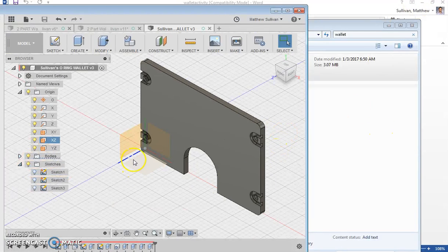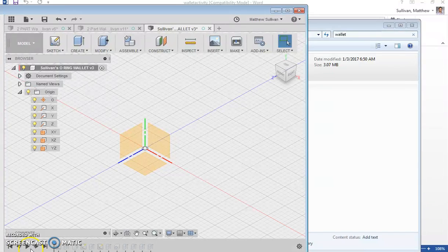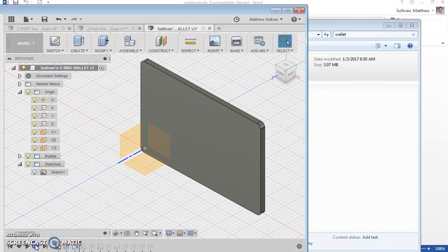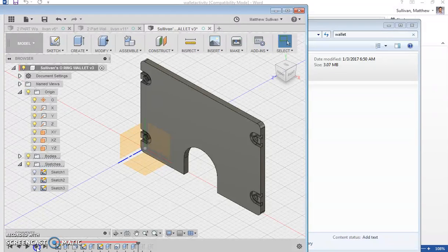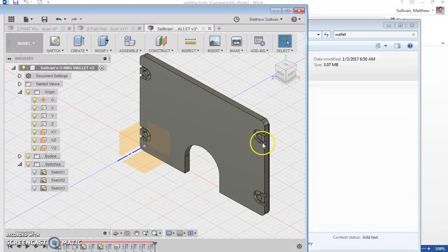So we're going to go ahead and get started with a sketch, extrusion, and then start modeling each of the parts out. This is kind of how, just to give you an idea from start to finish, I started with an extrusion, fillets, another sketch on the face, and then an extrusion, more sketches and extrusions, holes, and then I just cleaned up some little spots here at the end. Open everything up, and then I would also import an SVG, whatever type of design I wanted on the face.